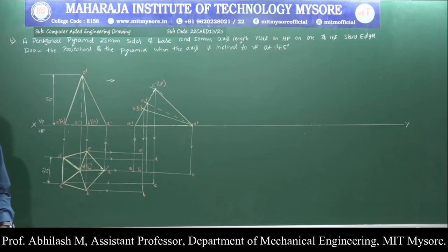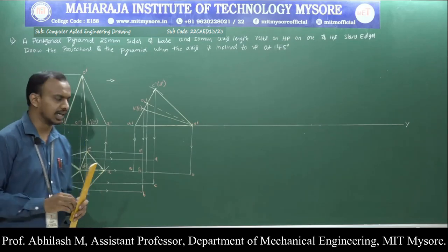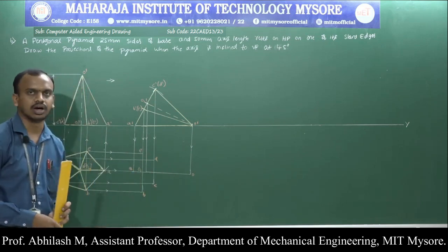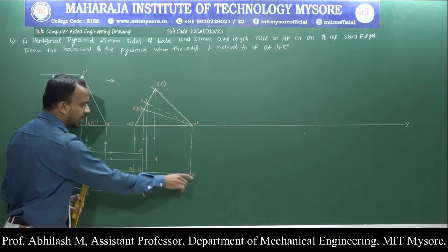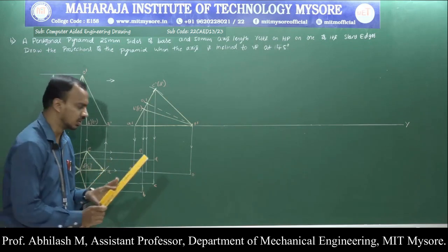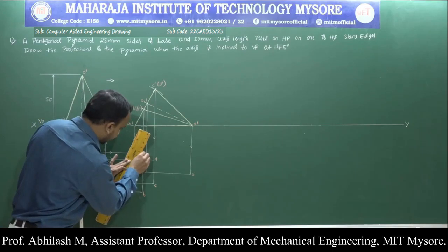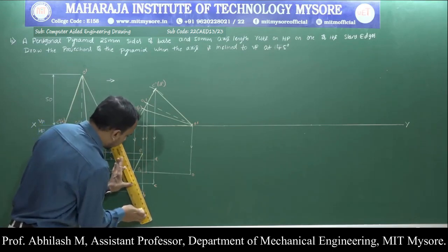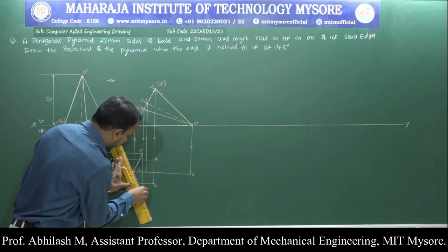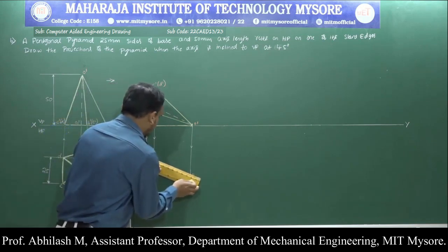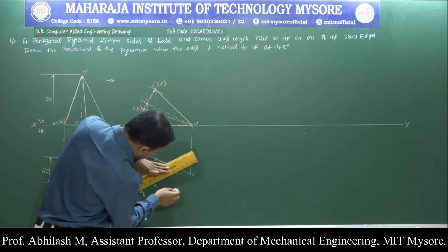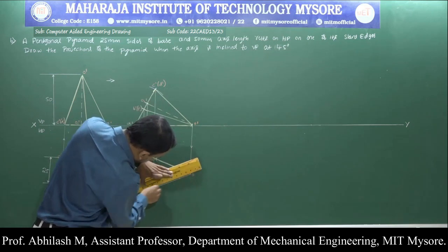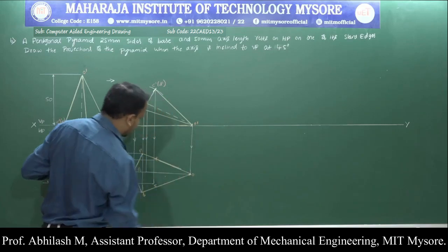Now we have successfully transferred all the points or the projection lines. What is the rule that we are supposed to apply? There are certain conditions that we know. The first condition is such that all the boundary edges or the faces are clearly visible. Which are the boundary edges or the faces? A to E is one side, A to B, and from O to B and E to O. That is completely visible according to the rules. So first make that happen, that is condition 1. From E to A it is completely visible, the outer side. From A to B, again from E to O it is the outer boundary. Again from B to O.